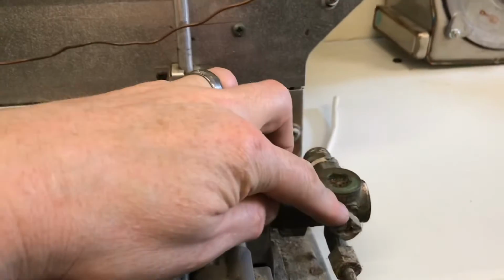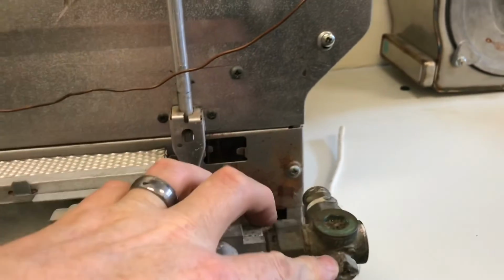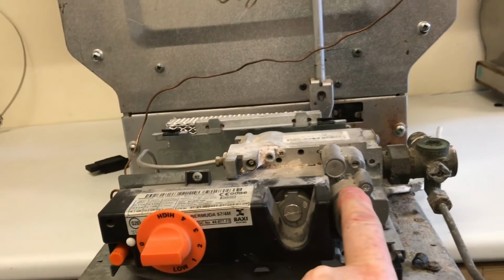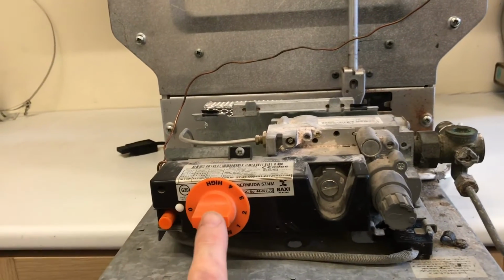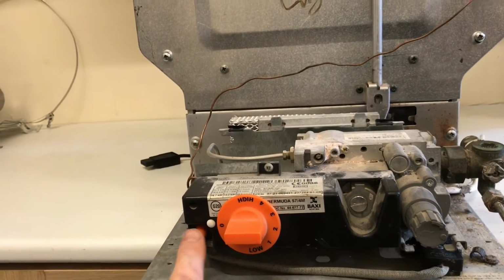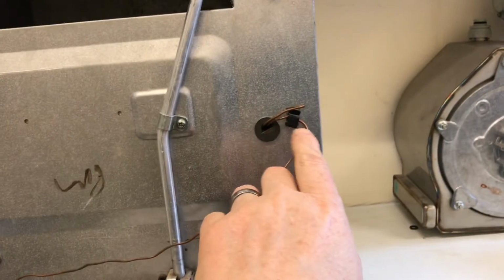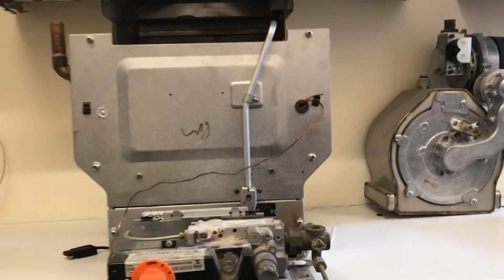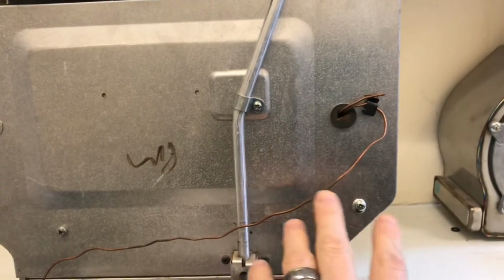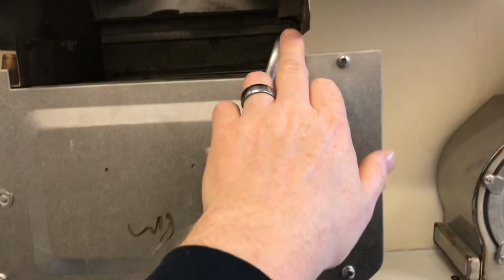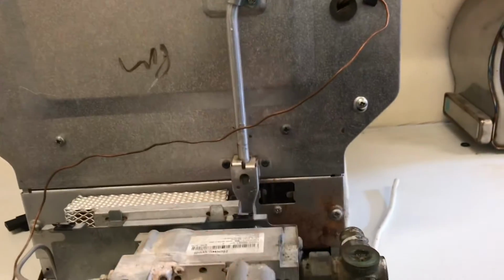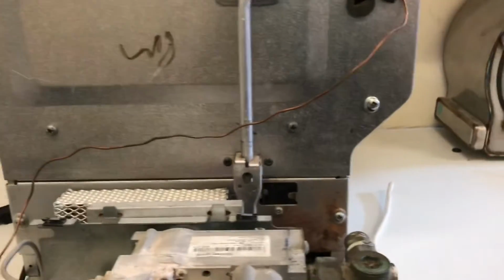Again, this is the gas isolation valve. Remember, all gas appliances need them. And this is the gas valve itself. And this is the thermostat and the igniter. Again, this lead you can see coming off here and going to here, that is the boiler thermostat. This little tube you see coming off here and going into the hood, this is part of the ASD, the atmospheric sensor device. It's a safety device.